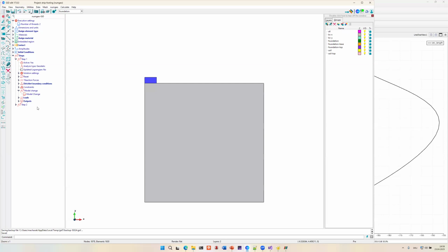That is, for example, maybe interesting. You could start with a simple model, Mohr-Coulomb model, to model different stages in the model generation. And then, for example, for a dynamic simulation, you could switch then to a SANISAND model or something, right? So you can change material models. That is already implemented. And we are currently working to implement two more options. The first option would be to add elements, and the other option would be to remove elements. And then you could, let's say, physically model excavation and build up.